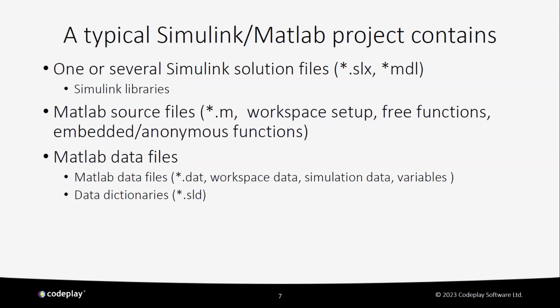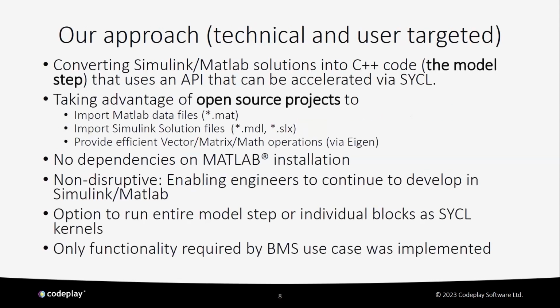A typical Matlab Simulink project contains the Simulink solution files, the SLX files or MDL files. The SLX files are essentially XML files. Then it can also contain Matlab files. They can be workspace setup files, but also free functions that can be called from other functions or from the Simulink model. There can be embedded functions in blocks and anonymous functions. And then you have Matlab data files, which use a proprietary binary format and contain workspace data, simulation data, all those kinds of things.